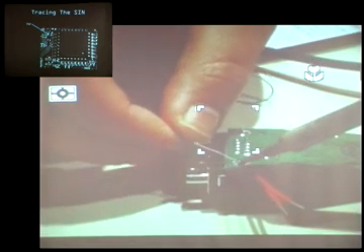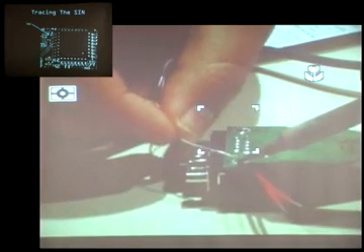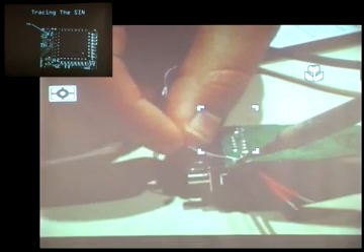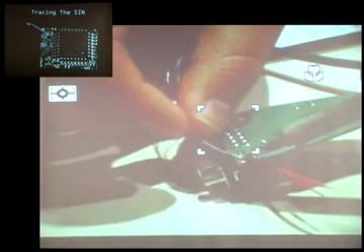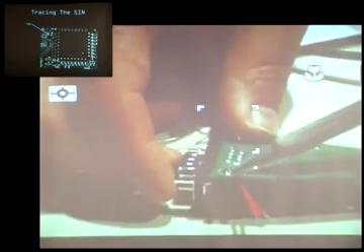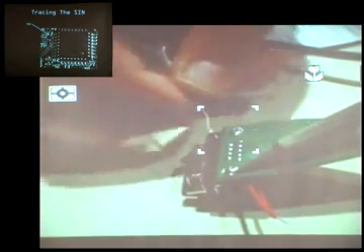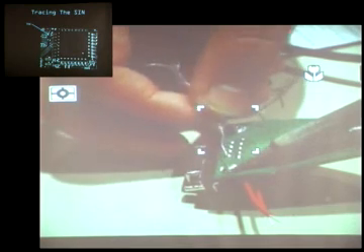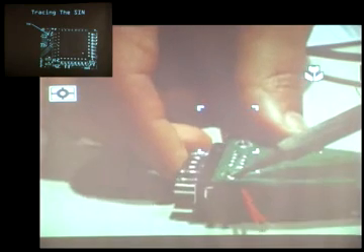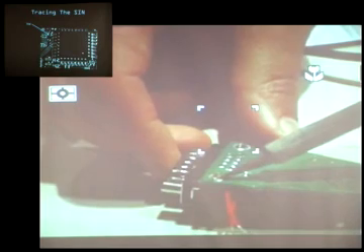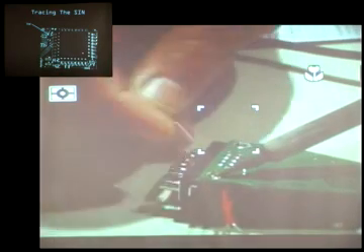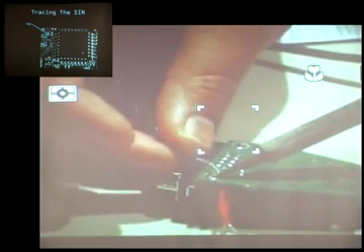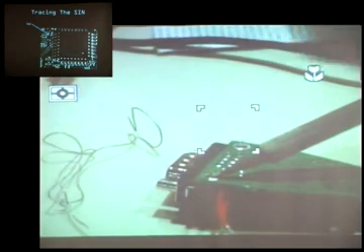So what I'm doing, this is a big piece of metal. I'm actually pre-soldering. I'm adding solder ahead of time to increase the contact area between the soldering iron and the workpiece until I can see the phase change happen in the solder itself. I'm having a little trouble pulling it down because of a funny angle. But eventually, there you go. The whole thing just melted and the soldering iron sort of sank into it. There you go. Okay, now where's the metal?